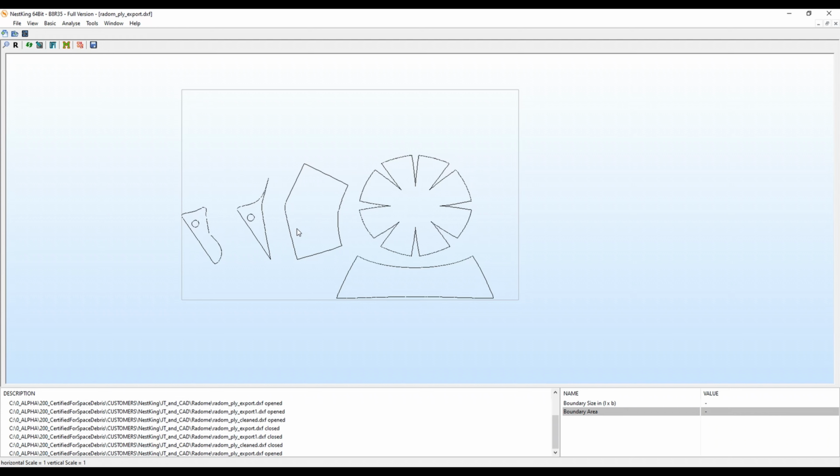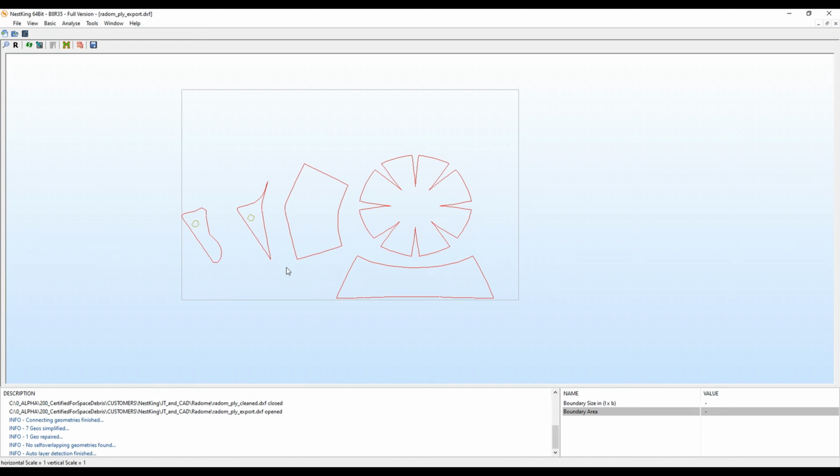All your draft plies are segmented or faceted from many small lines, and this is not very handy when working with your geometry. Therefore, we have a function called optimizer. This optimizer needs a tolerance, 0.1 millimeters is well enough, and it automatically finds the outer and also inner geometry.